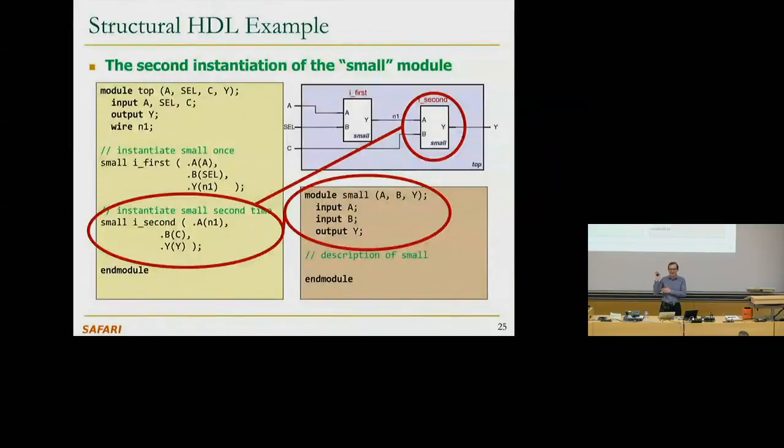Is it good? Cool. It's a different type of programming language, and actually one of your colleagues over here made a good point that I'm going to repeat over here. It's not as similar to other languages. You're used to programming with functions, right? This module is kind of like a function over here, except the return value is not there, right? The return value is actually somewhat encoded here. Basically, the function's output, you can think of it as the return value, is y, and you connect the output to the wire and 1 that you declared over here. Basically, you can think of these as return values, but you need to connect the return value to an output.